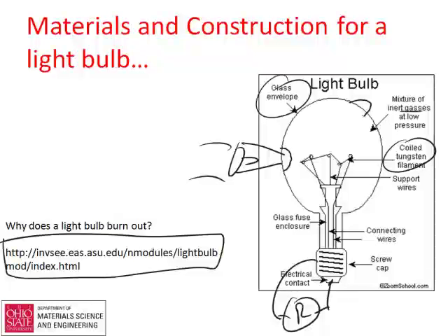And then the other things you can do, and Andy and Debbie and others do a great job of this, you can cut the casing off the light bulb, get at the filament, look at that with a classroom microscope, measure the resistance of that, uncoil it, and see that there's a huge length of wire associated with that. Once you take the top off, you can plug in the light bulb, and it will last for maybe 1.5 seconds, and it goes poof, and there's some nice white tungsten oxide smoke that comes off of that. And there's lots to discuss on why you use the materials you do, resistance, engineering against oxidation.